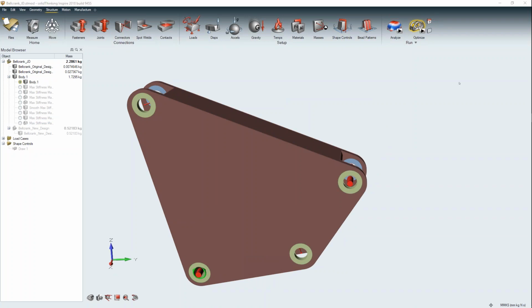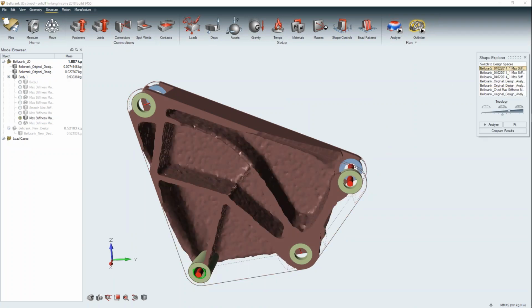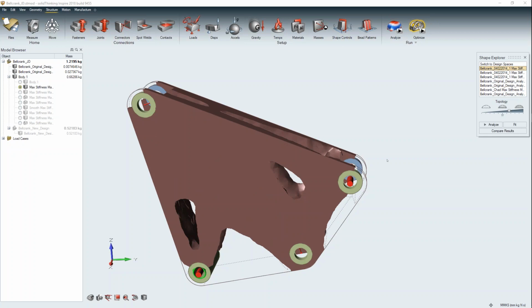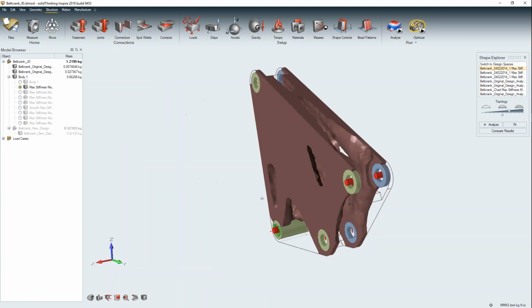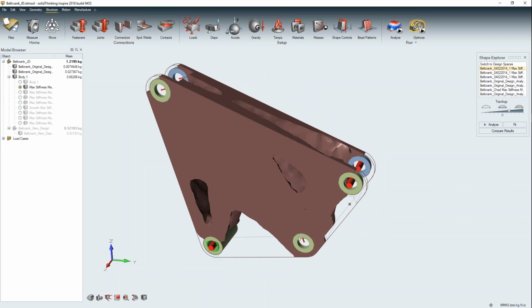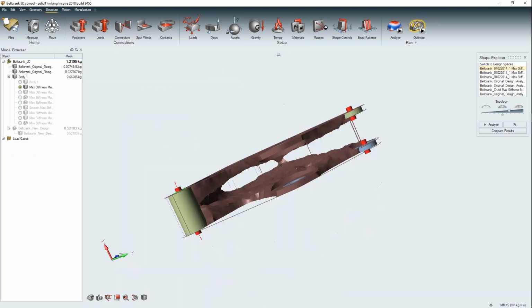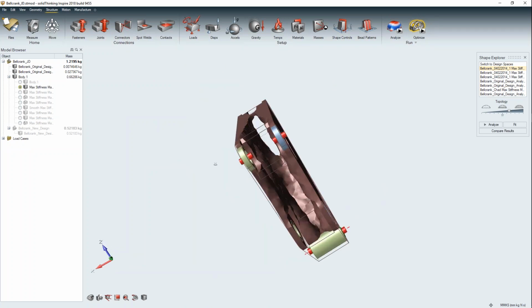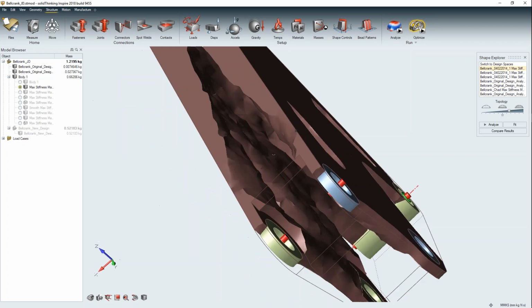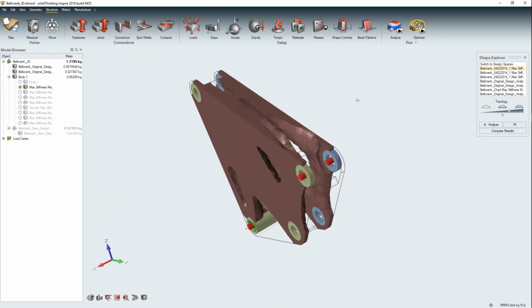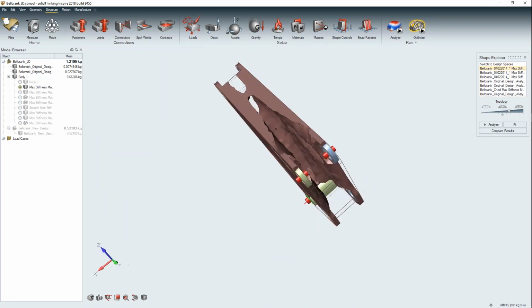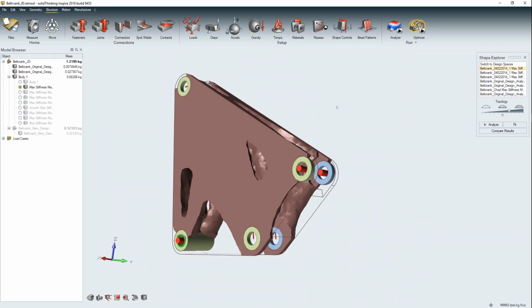those scenarios. The design Inspire comes up with satisfies all the loading conditions for that particular part, not just one, but all the operating conditions or all the worst case scenarios. And you can see the very first design it came up with basically hollowed out the part. You put all the material on the outside, added a couple of holes to reduce the material. And if you look at nature, this is the best possible design anyways, where the material is on the outside, good design for forces, moments, torques, but not necessarily easily manufacturable at that point.